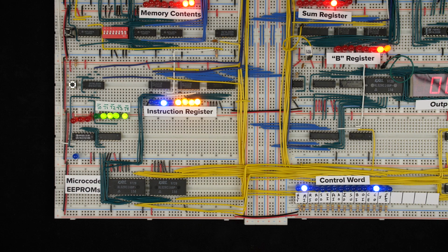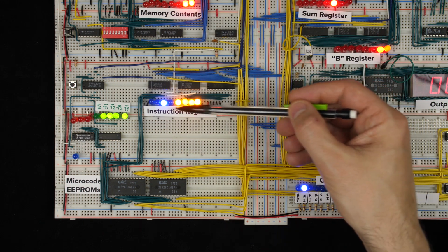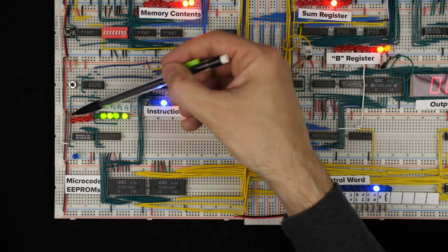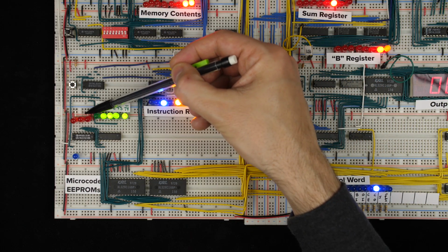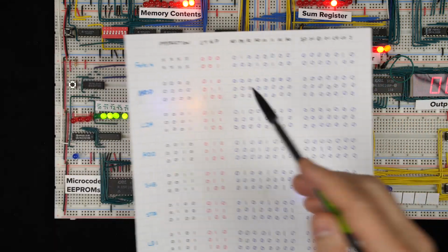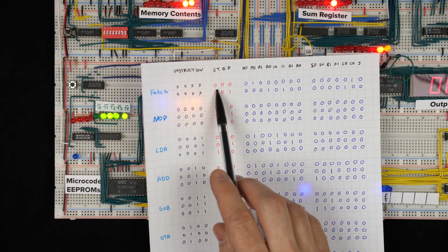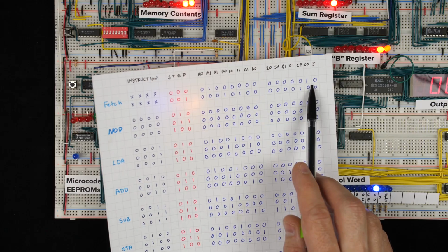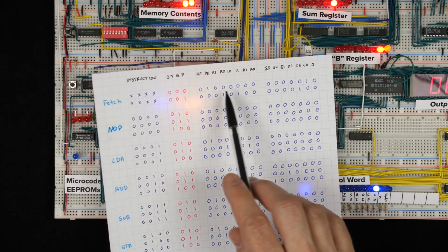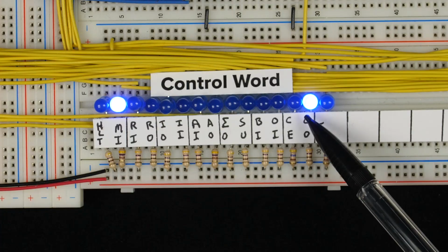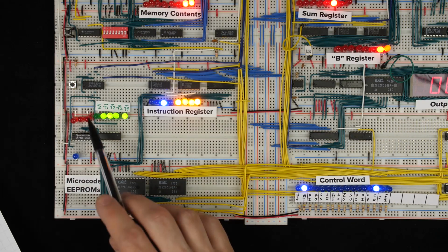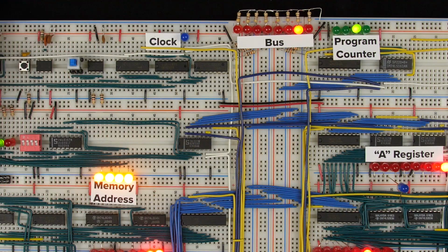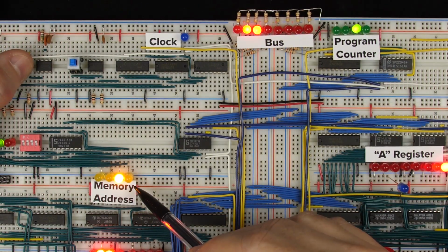So let's say there's a jump 0 instruction sitting in memory. First it gets loaded into the instruction register. That's because the step counter right now starts out at 0. And the EPROMs are programmed so that for any possible instruction, if the step is at 0, then output this control word. This control word says counter out, memory address register in. You can see that here, and that's because we're on step 0. So the contents of the program counter get put into the memory address register when the clock ticks.